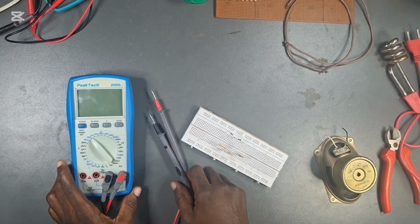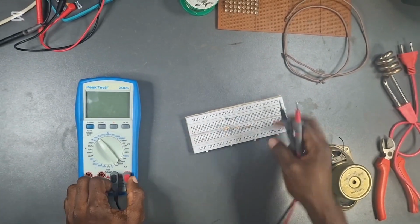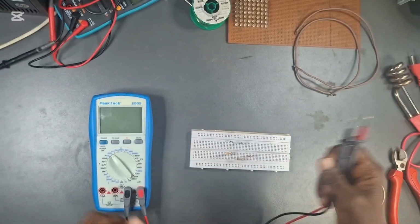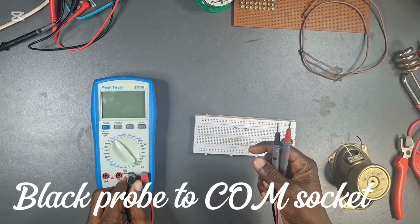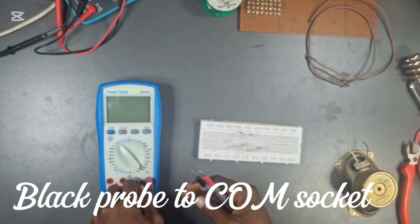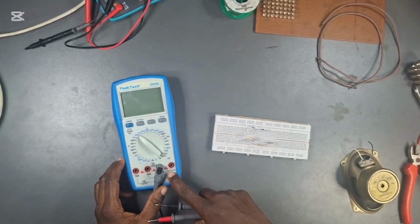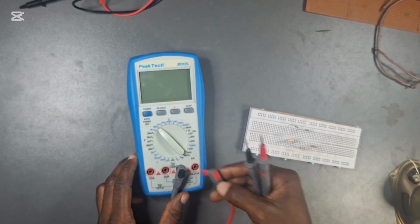So we are ready to go. Now, we're going to perform our resistance measurement. So always make sure that these are the probes. Always make sure that the black probe is plugged into the common socket, and then the red probe is also plugged into the red socket where we have the omega symbol. Always watch out for the omega symbol for resistance.